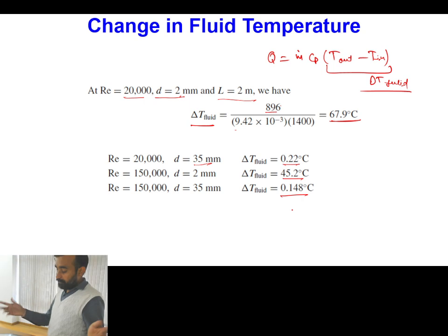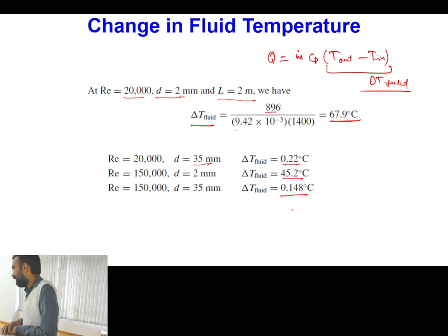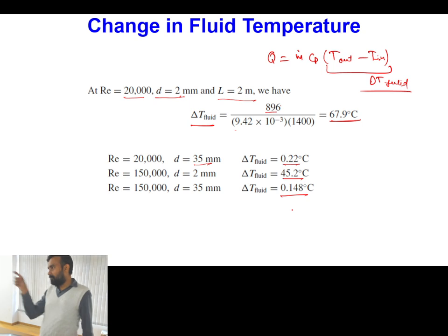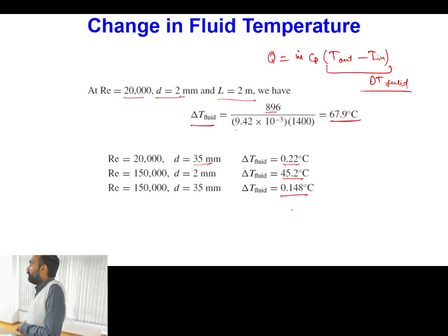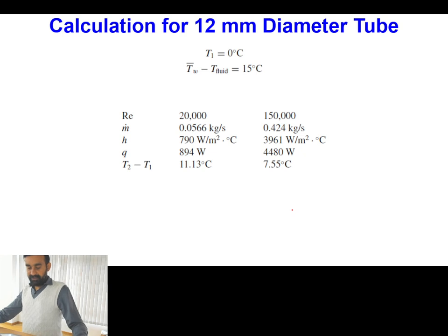As I told you, it may not be true that the actual data will come exactly at these values, but even if there is some deviation, the actual data will be close to these values. If you do not have any information available before planning the experiment, then how will you select the flow meter or the temperature measurement device? So we have to do some approximations based on the known theories before starting the experiment, and based on that we can determine all our parameters.